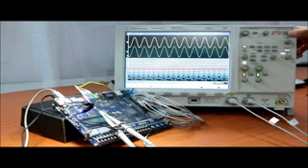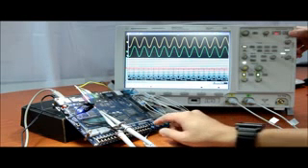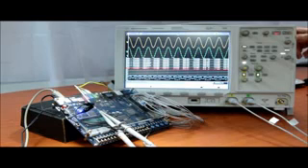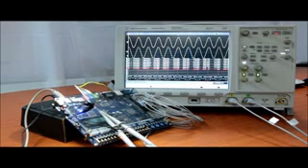Input a 100 Hz tone into the DE2 line-in jack. Observe the waveforms on the MSO with slider switch SW1 in the down position. Enable the 4-bit quantization by changing the slider switch to the up position. We can notice a significant quantization effect on the channel 2 100 Hz tone. The quantization effect is similar to noise in a signal, and this type of noise is called quantization noise.